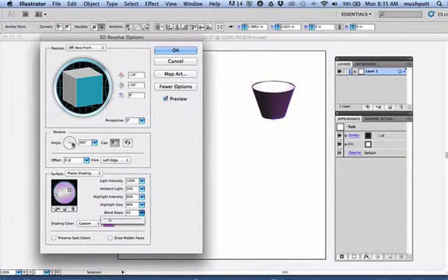Next, you might choose to not have a full 360-degree revolve. That means this full circle that your drawn path has taken will only revolve part of the way, and watch what happens. Okay, now you can see it disconnected here, but you don't really see what's going on. So let's just click and rotate. Click and rotate, and let's see. All right, so we're seeing directly into the shape at this point. I'm going to take us back to 360.